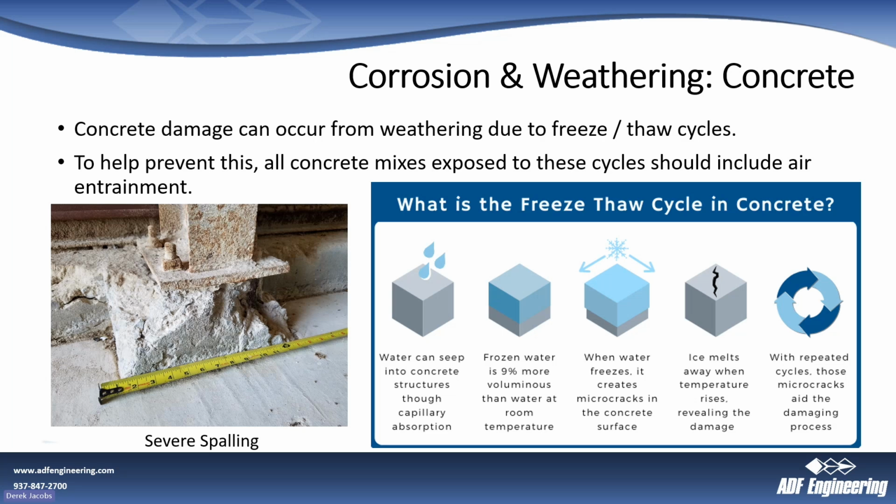And then if it's warmer out, water will get in, then it gets cold, the water will freeze. Obviously ice takes up more space than the water. It pushes the concrete, causes cracking. Microscopic cracks form, that allows more water in, that cycle repeats,